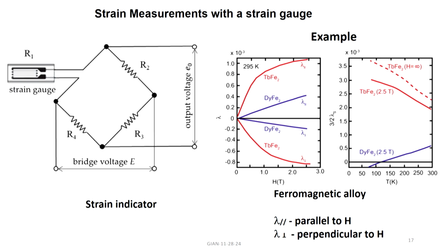And I showed this earlier, this is the strain gauge, it forms a Wheatstone bridge. The bridge output goes to the strain indicator, and whenever there is strain, the resistance of this arm will change, leading to a condition away from balance. The strain indicator will correct for that and will produce an output which will show the strain in parts per million. Okay. So, you can directly read what the strain is, and it can be measured parallel to the magnetic field or perpendicular to it, it does not matter.